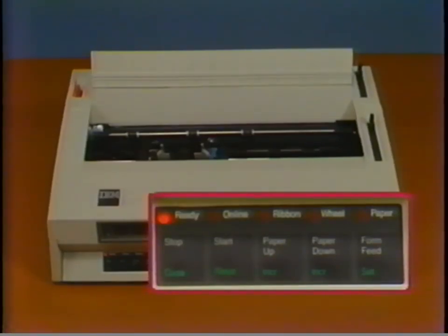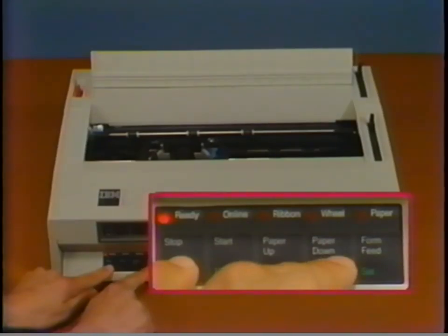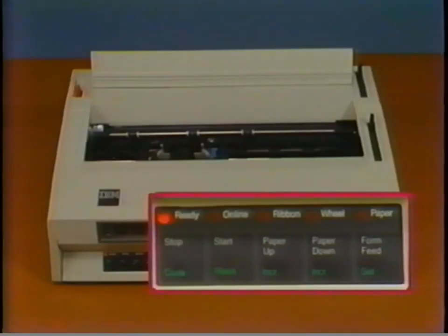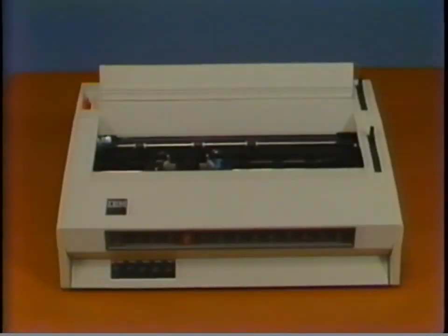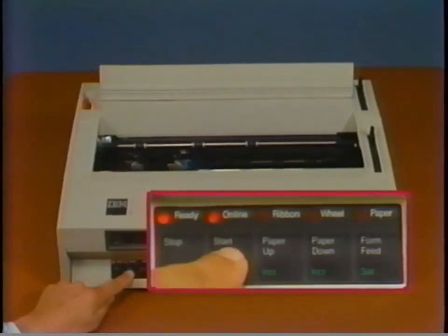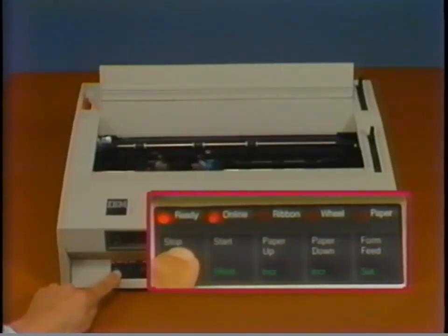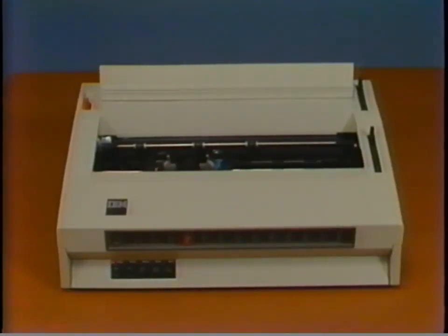When you hold the code button depressed and operate the paper up, paper down, or form feed buttons, these buttons perform a second function. These are micro up, micro down, and set first writing line. The start button changes the printer from being offline to online. When the printer goes online, the carrier moves to the left margin and the online light turns on. The paper move buttons are active only when the printer is offline.